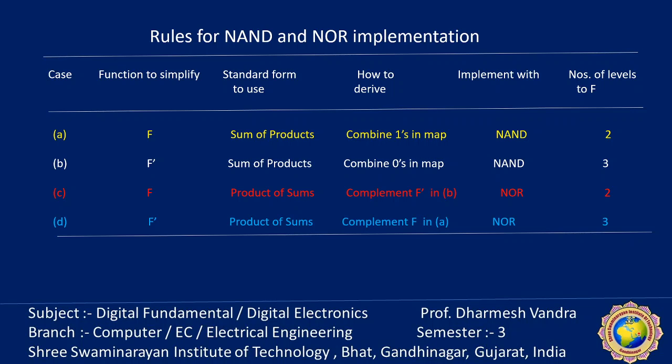Remember that. From the transformation, we conclude that the Boolean function can be implemented in 2-level NAND gates. The rules for obtaining the NAND logic diagram: first, we simplify the function in SOP form. Then draw the NAND gate for each product term with at least 2 literals. The outputs of these NAND gates are given to the second level. Draw a single NAND gate with an inverted-OR graphic symbol in the second level and combine them. So it requires only 2 levels of NAND gate logic.